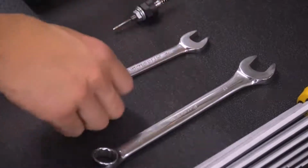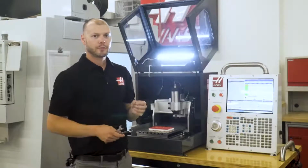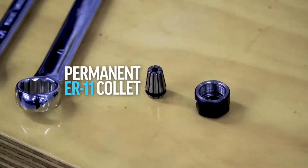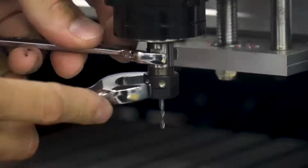So, I have my 1/8 inch 3-flute end mill, and I'll tighten this in the spindle. I should mention, the spindle has a permanent female ER11 collet interface for the spindle nose, so you'll need a set of ER11 collets for each machine. Now, I'll tighten my tool in the spindle. It's a small tool, so don't over-tighten it.